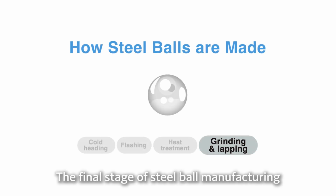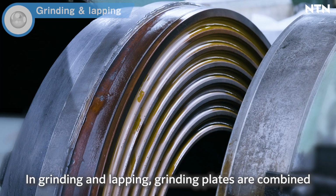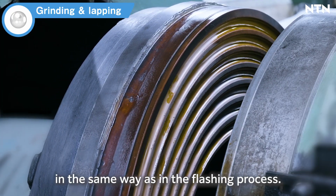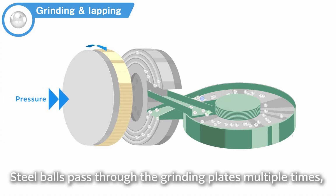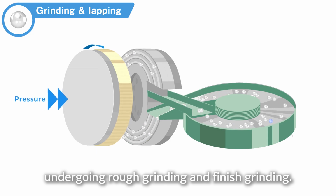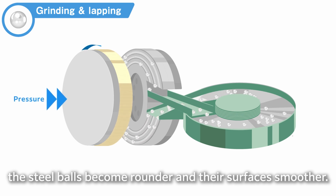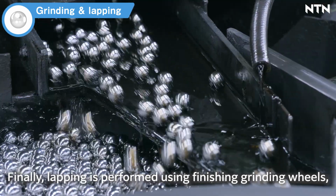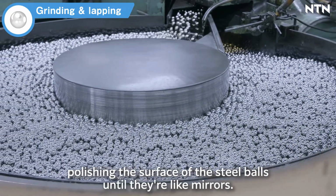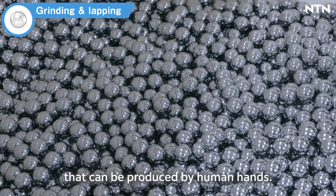The final stage of steel ball manufacturing is grinding and lapping. In grinding and lapping, grinding plates are combined in the same way as in the flashing process. Steel balls pass through the grinding plates multiple times, undergoing rough grinding and finish grinding. During this process, the steel balls become rounder and their surfaces smoother. Finally, lapping is performed using finishing grinding wheels, polishing the surface of the steel balls until they're like mirrors. This results in the roundest ball that can be produced by human hands.